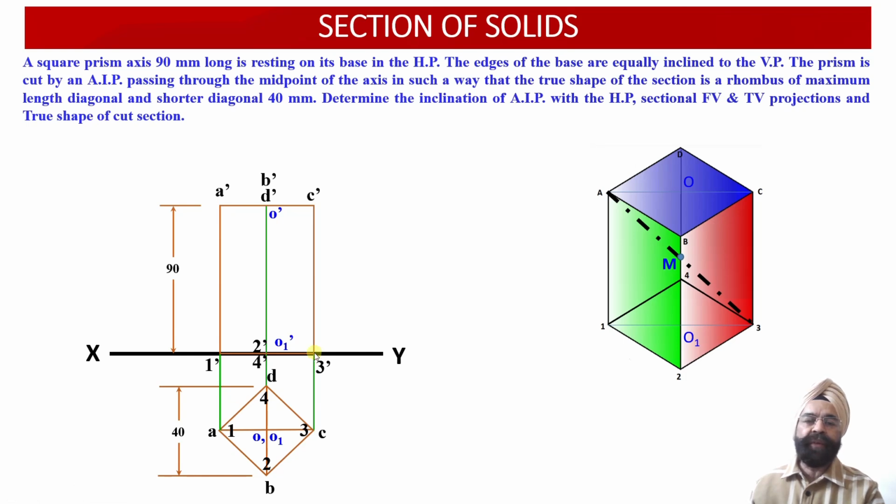One thing here we must remember is that this vertical edge D4 happens to lie on the rear side of the solid. So the projection of D4 in the front view, that is D dash 4 dash, should have been drawn as a dotted line or hidden line. But this vertical edge D4 has coincided with, or been superimposed by, the vertical edge B2 in the front view projection.